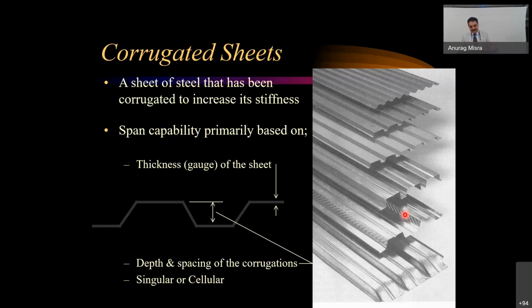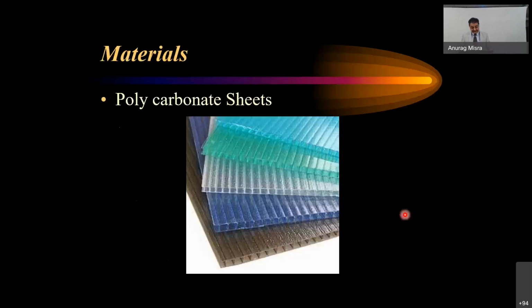The steel deck is used, and then you place the reinforcement on top of that, and that serves as the sacrificial shuttering. So that is enhancing the speed of the construction substantially, because if you are doing some bridge or flyover or elevated road inside the city, it is very difficult to block the traffic for longer periods. So this technology is helping us quite a lot in dealing with this situation, and the pace of construction becomes very fast.